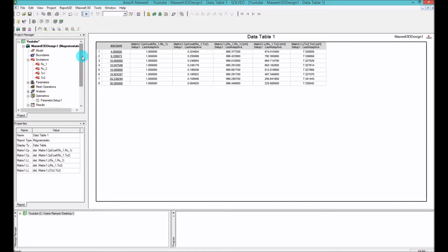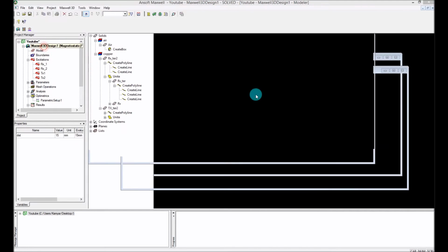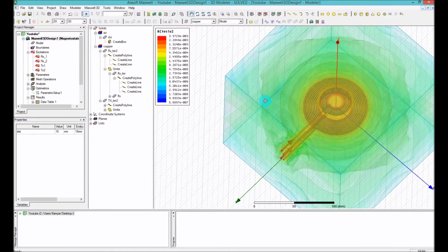But now I want to import all these important values into Simplorer, and use them in order to apply some actual current and actual voltage. I also want to put a capacitor in series to see if magnetic resonance is going to help the power efficiency and boost it up, and things of this nature. So let's start from where we left off last time, which was here.